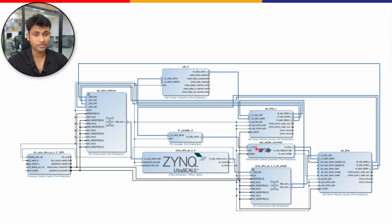Next, let's take a look at the AXI4 stream subset converter, which converts AXI streaming signals between different formats, ensuring compatibility between different IPs and components with different AXI interfacing specifications. So it plays a key role in adjusting data paths between the DMA engines, the filters and transforms, and this is what we had looked at in the resizer application as well, where we had created such a subset converter using the HLS tool.